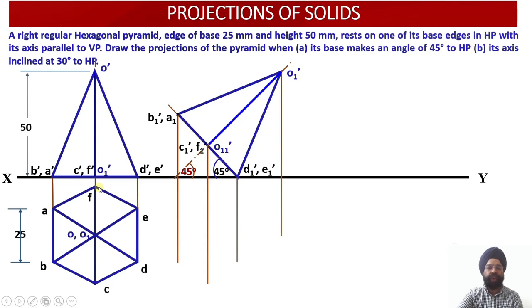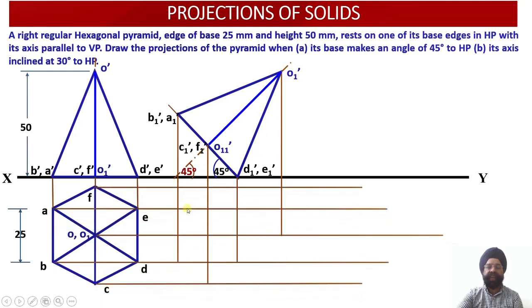So the horizontal projectors from the plan projection view, that is the previous plan projection view, will be drawn, and the vertical projectors through the elevation view which has been drawn will be worked out, and we will work out the corresponding points of intersection. Wherever the points of intersection are, the coordinate locations of the points in the plan view will be located. So just see, we draw the vertical projector through A1 dash and draw the horizontal projector through the plan projection view, that is the previous one. Wherever these two intersect, we get the location of point A1.